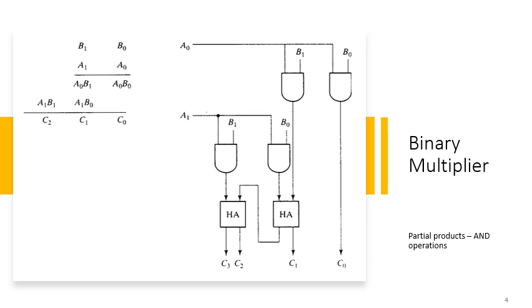The first product operation, multiplying A0 with B0 and B1, is known as the first partial product. Then we move to the next placement. For the next multiplication, we move one placement further and multiply A1 with B0, giving the product term A1 B0, and then A1 with B1.